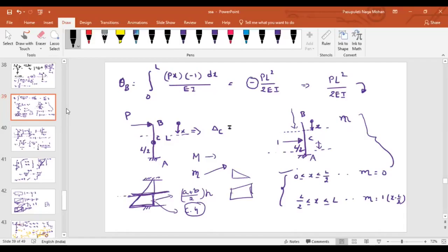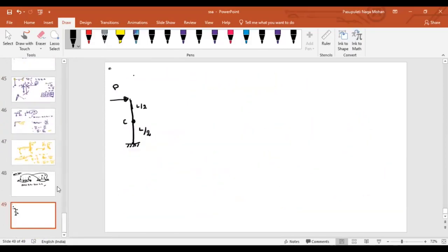No, sir. Now, let me make it easier for you by using the reciprocal theorem. Let us say, what will be the deflected shape? I am drawing an enlarged shape so that you can understand. I am applying the load here and the deflection here, let us say delta C. Now, in the second case, I will apply the same load at point C, and I will measure the deflection at B. Let us say this is delta B.